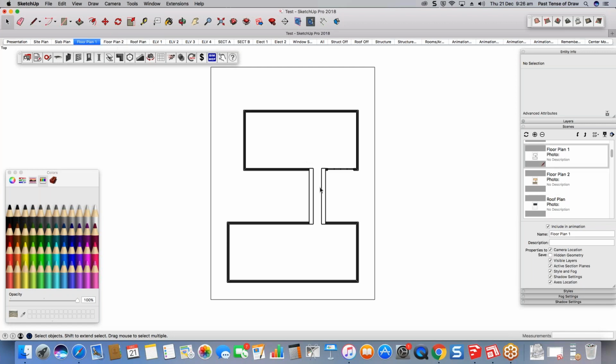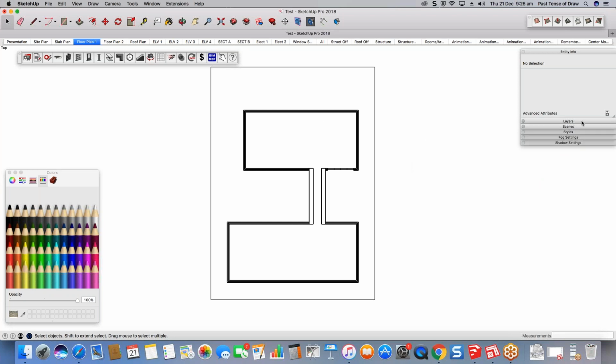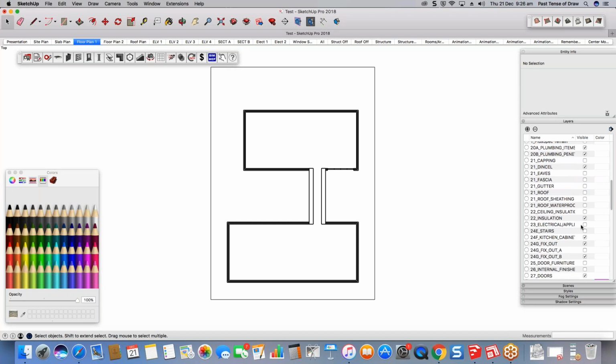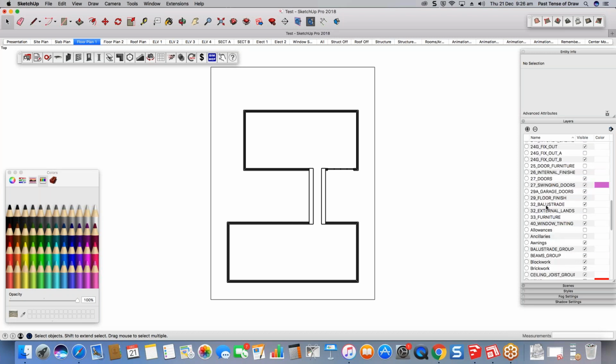Now, there's also other things going on here. We are teaching PlusSpec what we want to be visible. So if I was to drop in different kinds of furniture and all those kinds of things, it might not show up in my floor plan. That's because the floor plan templates have been set up by default to turn off furniture. So they're more of a dimensioning plan. But if you want to turn it into a furniture plan, simply turn on your furniture and then right click